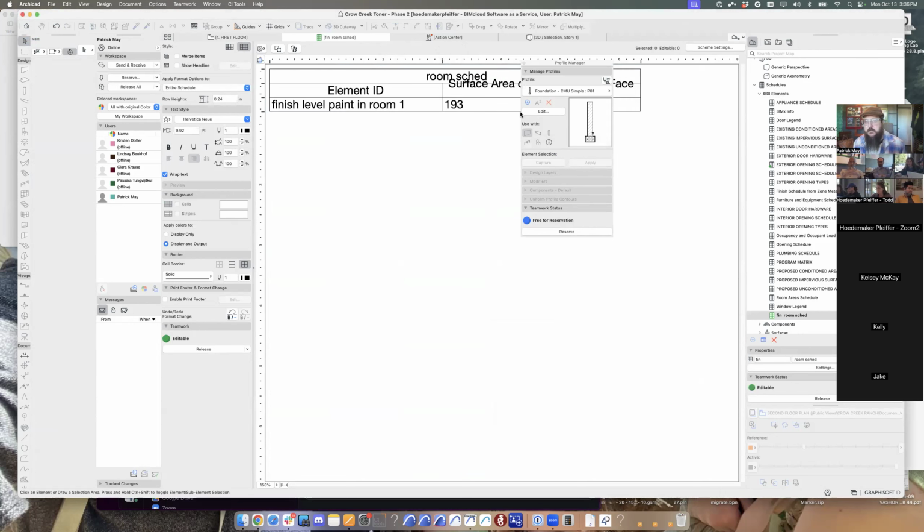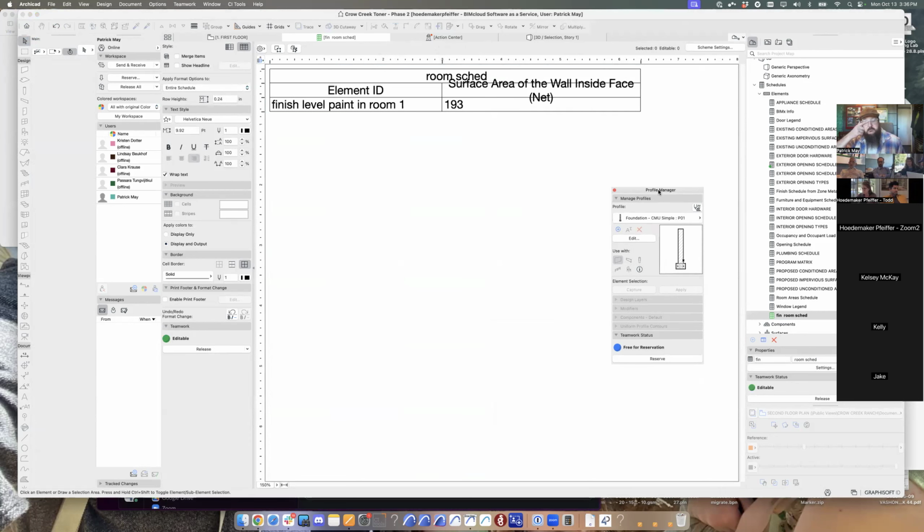For example, we draw all of our 5/8 inch drywall at 3/4 of an inch because by the time they mud over and everything, it adds a little bit of thickness. In reality it's a little less than 3/4, but whatever. We could start with a 5/8 inch typical substrate, and then if we know it's going to be paint, we'll just add an 1/8 inch layer on top of that. That schedules all the way around. It essentially means we have to apply a second layer of finish to every interior wall surface, which you could argue is good or bad.